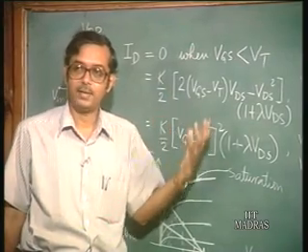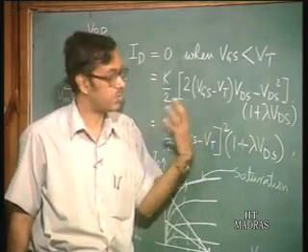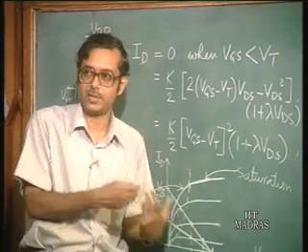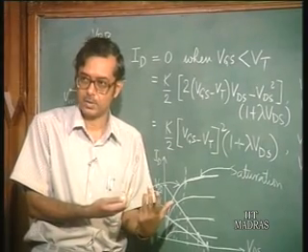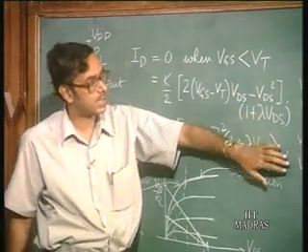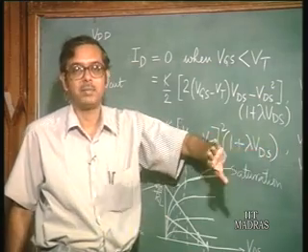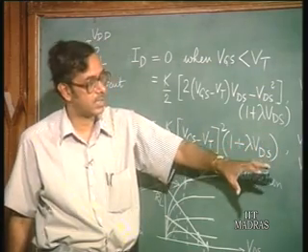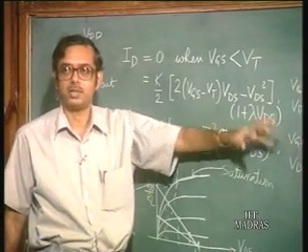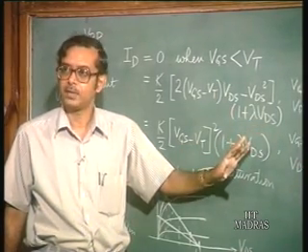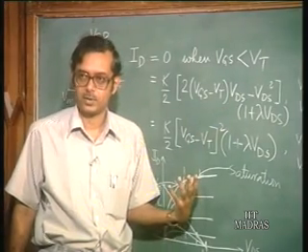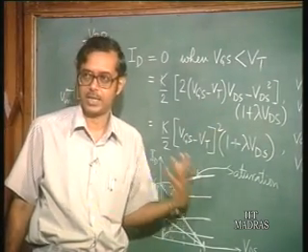And when the gate to source voltage is less negative compared to the pinch off voltage, you have a channel. So, it is a similar type of relations; you can think of it as the threshold voltage not being positive, but a negative number. Then it behaves in a similar fashion. So, that is what a depletion type device is.